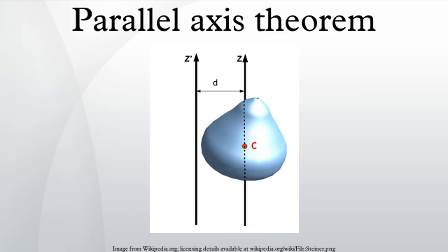So, the equation becomes I = I_CM + mr². Tensor generalization. The parallel axis theorem can be generalized to calculations involving the inertia tensor. Let I_ij denote the inertia tensor of a body as calculated at the center of mass. Then the inertia tensor J_ij, calculated relative to a new point, is given by the following, where R is the displacement vector from the center of mass to the new point, and δ_ij is the Kronecker delta.